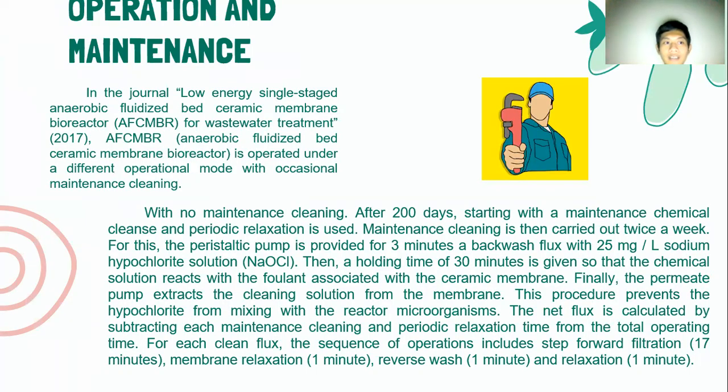Operation and maintenance. In the journal paper, Low Energy Single Stage Anaerobic Fluidized Bed Ceramic Membrane Bioreactor or AFCMBR for wastewater treatment, the reactor is operated under a different operational mode with occasional maintenance cleaning. With no maintenance cleaning after 200 days, starting with a maintenance chemical cleaning and periodic relaxation is used. Maintenance cleaning is then carried out twice a week.